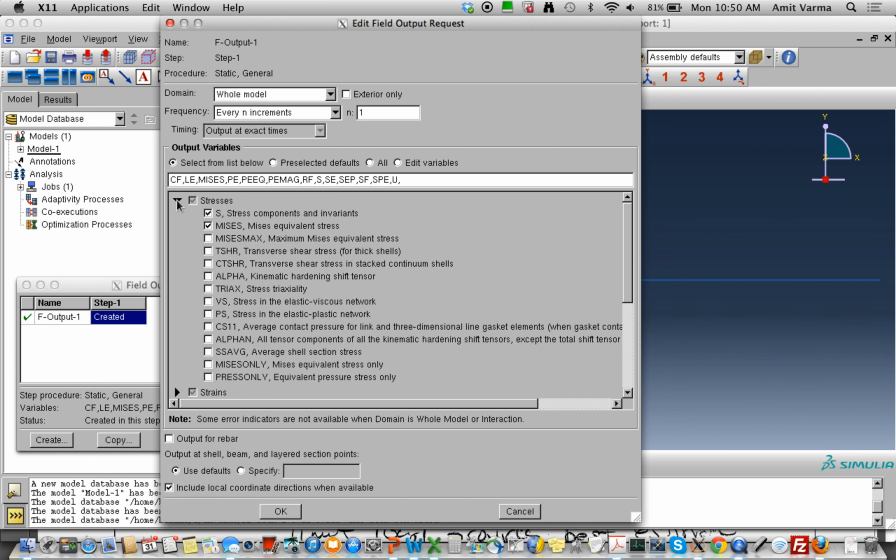So not all of U1, U2, and U3 will be restrained. In fact, U1 will be free at the node where you're applying the axial force. It has to be, otherwise the force will just go into the foundation. I thought of many other clever ways of giving you the problem.